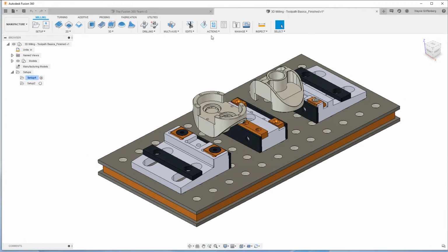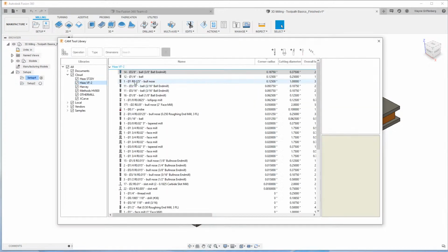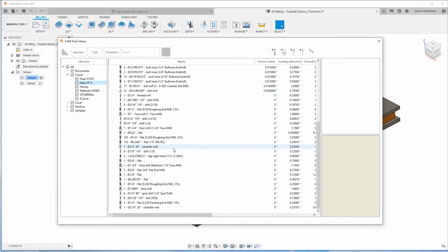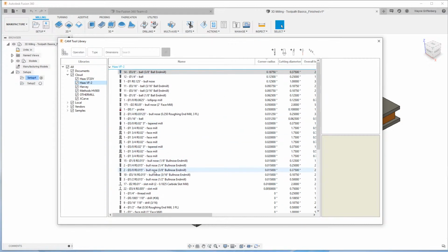So that will enable in your tool library this cloud library tool. So now you can create a cloud library like you see here for our Haas VF2. Start to populate it with tools. You can even import and copy tools. You can create them from scratch and work with those tools directly. And now each of your team will share the same library inside the cloud library.